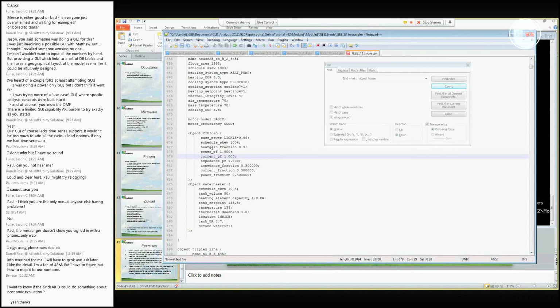So, on an individual customer, how did you affect their bill? Say there's 1,000 customers on this feeder. What percentage of them did their bill go up? What percentage did they go down? And then overall, you can look at it to say, okay, did I create a revenue neutral rate, so that the utility is still collecting the same amount of revenue coming in or out, which is typically pretty important to regulators. So you can start to evaluate some of those questions. But for the most part, what you're doing is using GridLAB to get the technical potential, and then using that technical potential to determine your economic value offline.